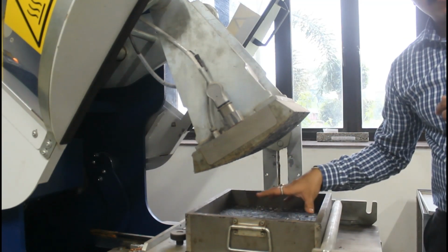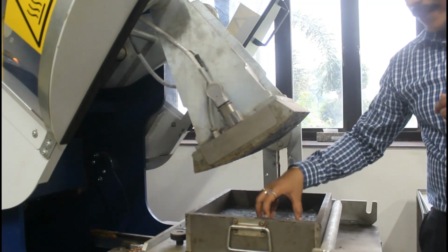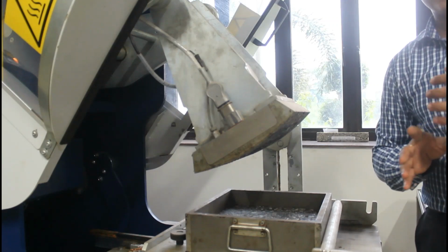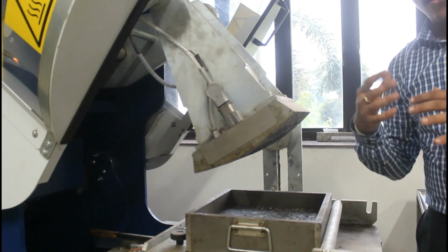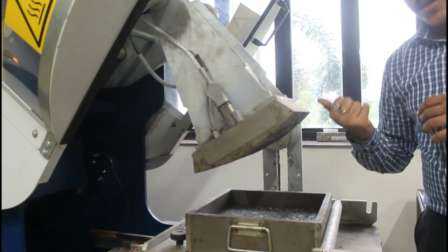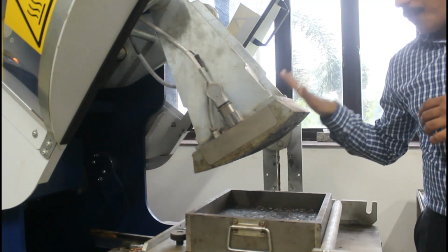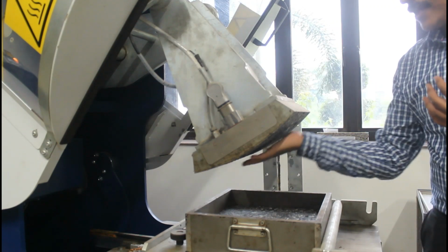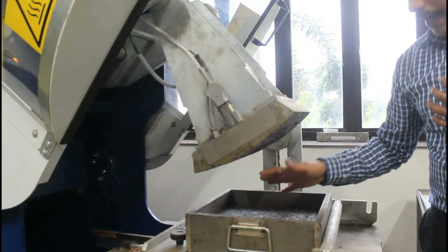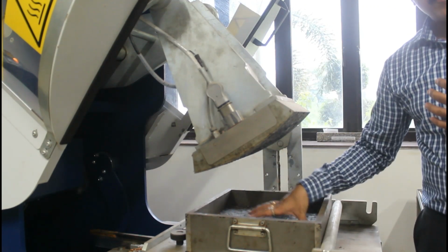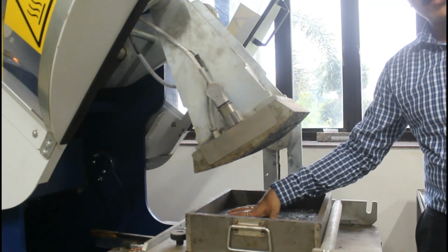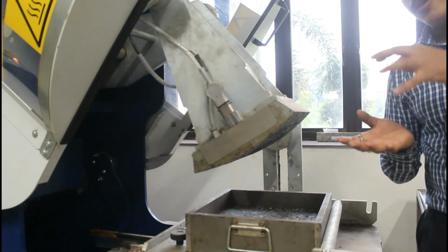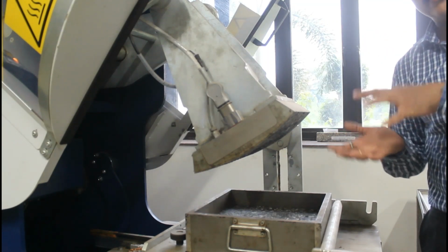This sample can be a lateral core. You can take a core, a cylindrical core, and further test for other properties, let's say modulus, dynamic modulus, or any other property as desired. So the compaction it applies is similar to the field compaction, because it moves like a roller to and fro, where it applies kneading action. Unlike the impact device of Marshall, it applies kneading action where the aggregate arrangement or aggregate configuration is similar to what is in the field.